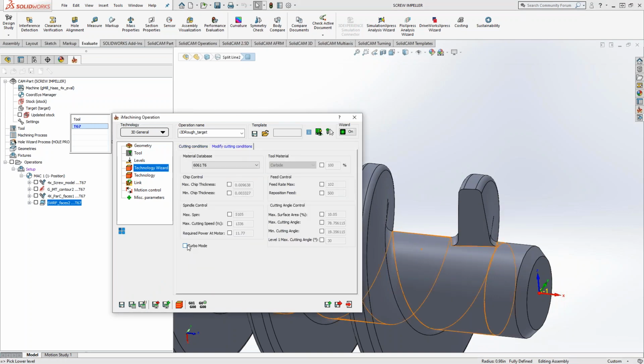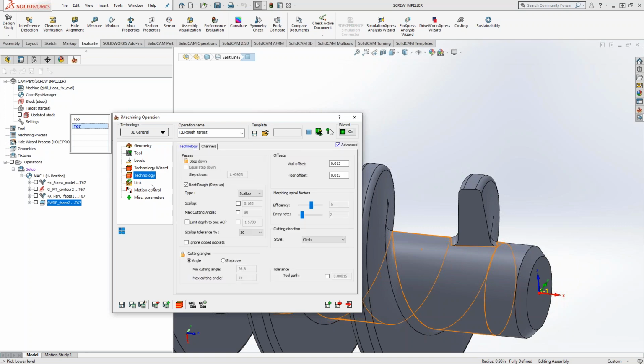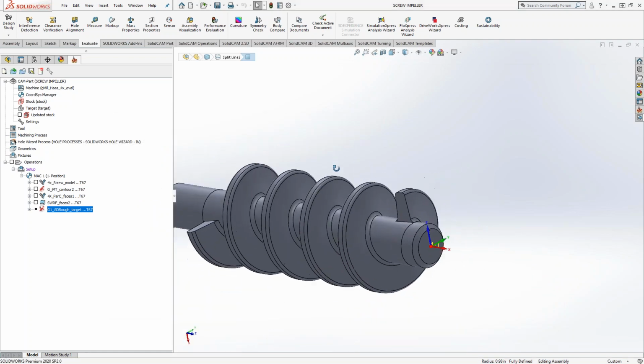So I'm just going to set this up exactly like a 3D iMachining. I'm going to put maybe a little more material so we're not here forever calculating this thing, but you can see that all the controls will be the same because again, we're still applying a 3D toolpath to a 3D part. The fact that the machine can index doesn't change anything with this. I'm basically just going to lock it in place and look at it like a 3D toolpath.